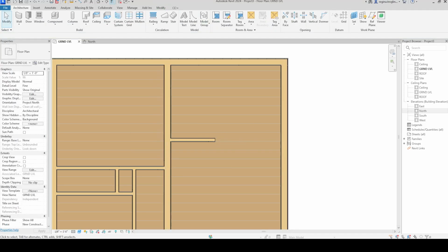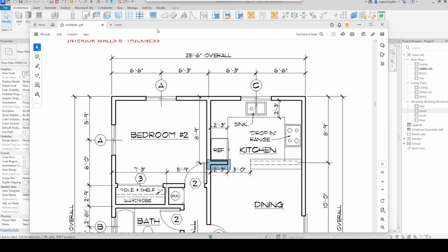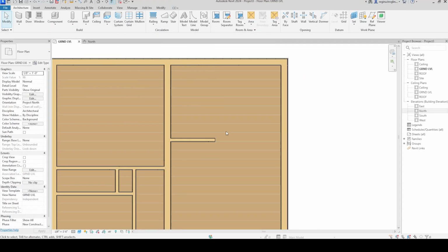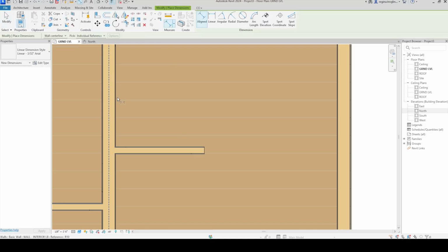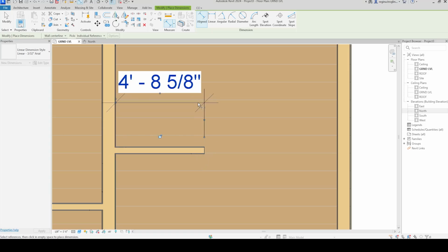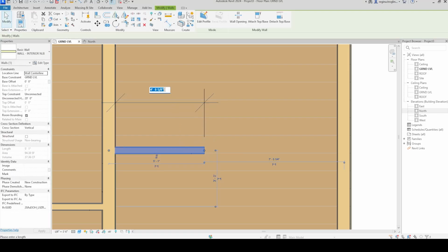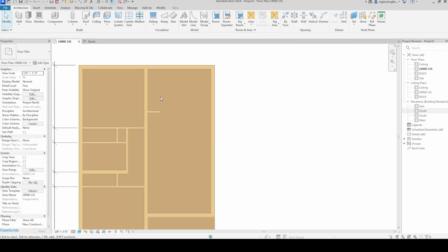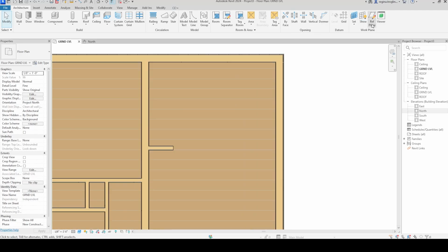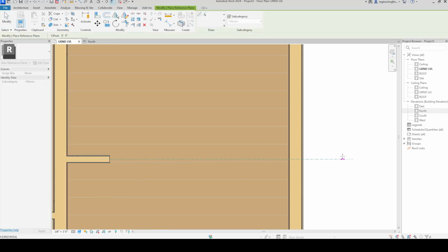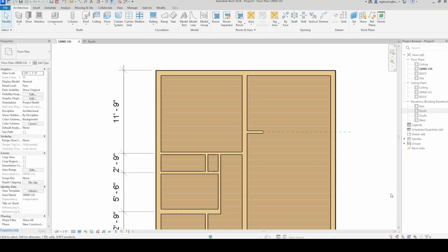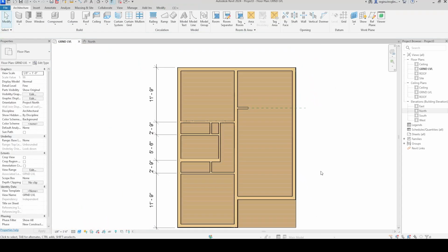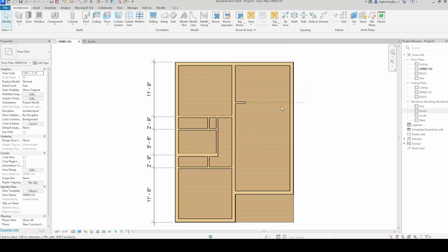And then if you notice on plan, this is not a full wall. It is 2'3" out. So the way that I like to do this is grab this exterior wall and grab the edge of the wall here. There's that. And 2'3" and make it tiny. Again, I'm going to chain these dimensions. The other thing I'm going to go ahead and add, because there is a counter, is I'm going to center line a reference plane here just as a reference for later. All right, and there is all of the interior and exterior walls all set, ready to go.